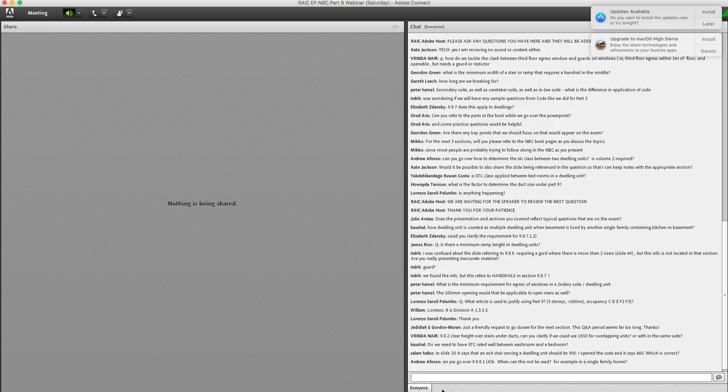Billy, I'm on the exact website on practice questions. I have another question here, and it is, could you clarify the requirement for 9.8.7.1.2? So 9.8.7.1 is on required handrails. Sentence 2 is on, except where a stair serves not more than 2 dwelling units, at least one handrail shall be located not more than 750 millimeters from the natural path of travel on the stair or ramp.